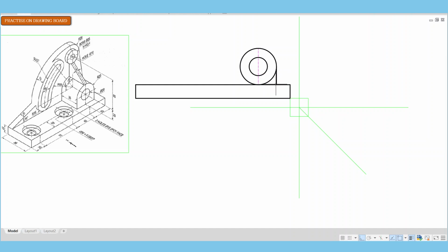So once I draw that with a circle, I can draw a line which is tangential to the circle, and then I project that line downwards like that. And now I can clean the unwanted parts of the circle. Because you are working with a drawing board, you may not have to go through this. You can just draw the semicircle instead of drawing a circle and cleaning a part of it.